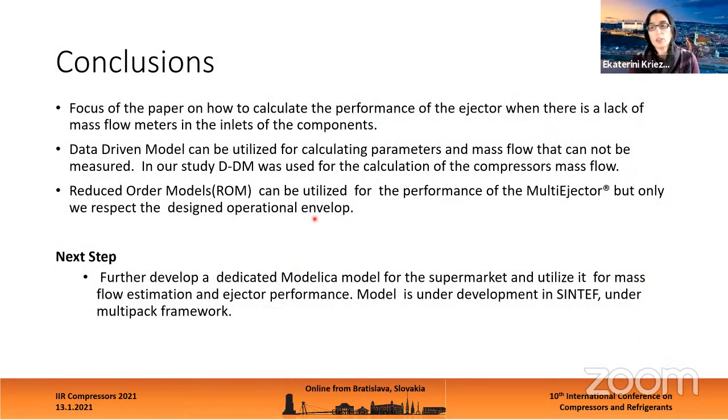To conclude, the work was to find a way to calculate the performance of the ejectors when we don't have the mass flow meter, so we lack measurements. It seems that the utilization of a well-trained data-driven model can support us. We can calculate the compressor mass flow from the data-driven model and utilize that in the calculation of the performance of the ejector. The reduced order model for a multi-ejector gives realistic results only when it's used inside the design operational envelope.